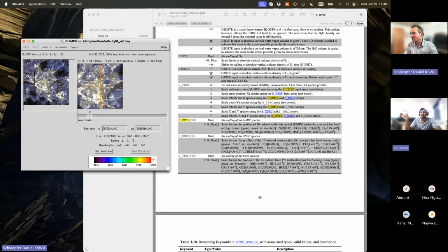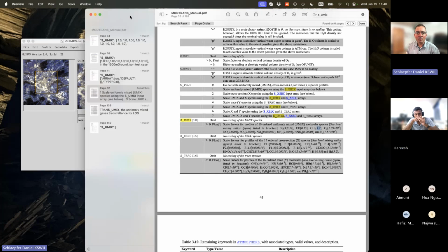So let's say we do have an ENVI license over here, and we do have Sentinel imagery over a region. Do I import the imagery into ENVI and convert it into a TIFF file, and then I can bring it here? Is that right? Yeah. So if you import it in ENVI and save as an ENVI file, then it can be used with our software.